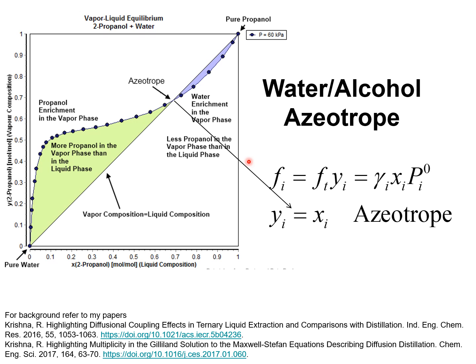But the use of such entrainers increases the energy consumption, and there is a need for more energy efficient ways to separate water alcohol mixtures than use of azeotropic or extractive distillation. One solution is to use a hybrid of distillation with membrane separations.